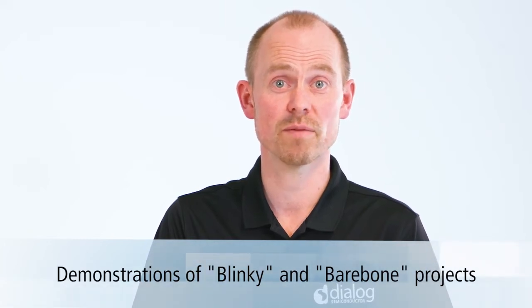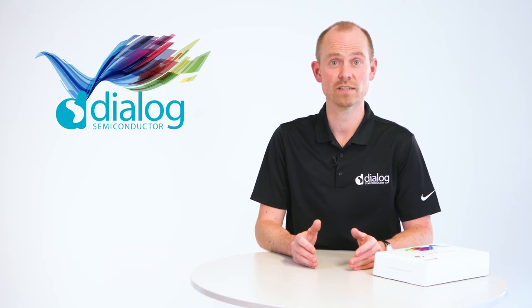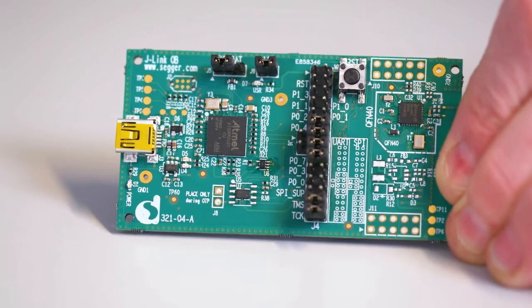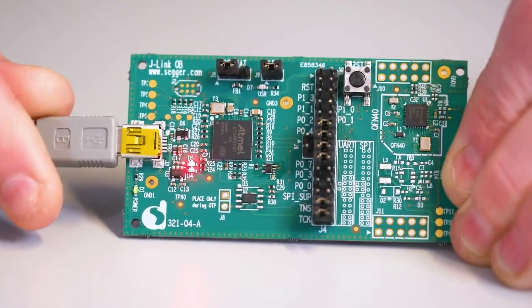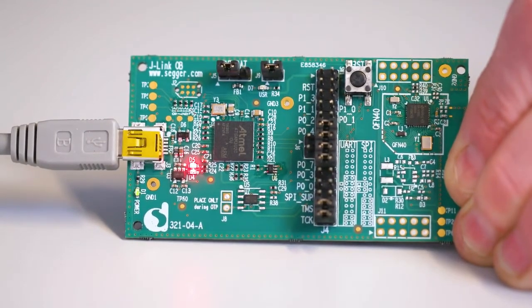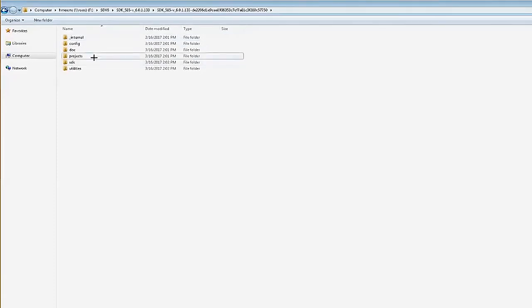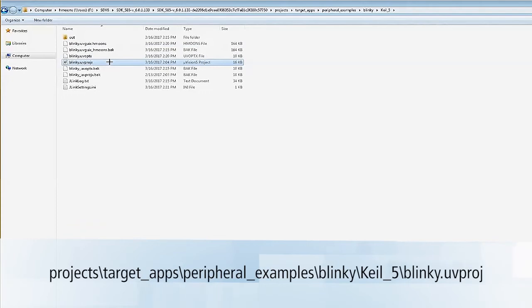Now we'll show you the step-by-step procedure to run the BLINKY project. We use this simple project to test run the functionality of the whole environment. The first step is to connect your DA14585 Development Kit Basic to your PC. This should be done using the micro USB cable. Also check jumper J9 to connect the LED. Now open the BLINKY project, which is in the peripheral example folder, like this. You can see the full path name on the screen.